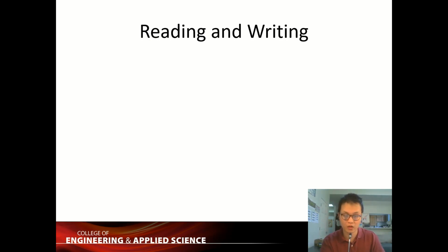So you need the address. Then you apply the data bits, which is the input, that must be stored in the memory to the input lines. Then you activate the write input, so you tell your write command yes. You activate the RAM to be able to get new information in.